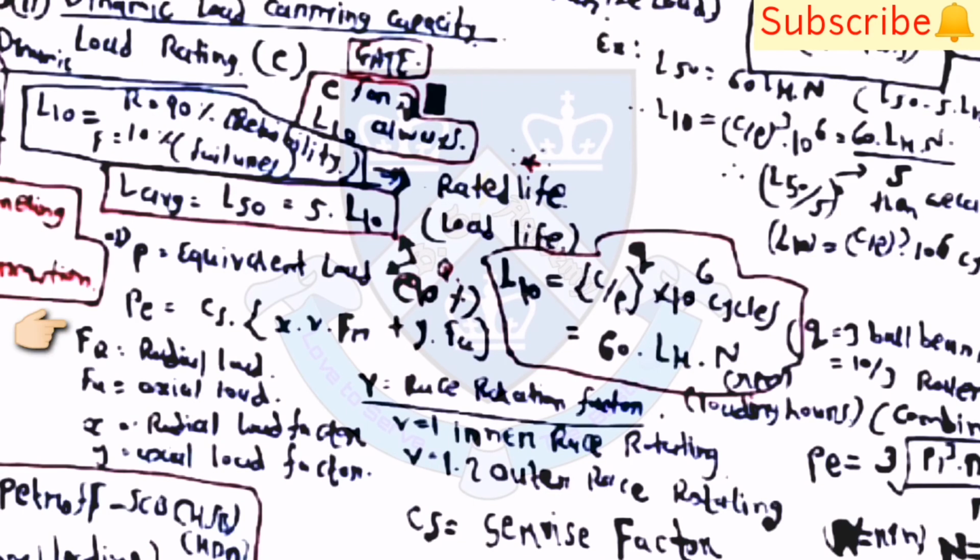Then PE is equal to CS into X into V into FR plus Y into FA. Then L average is equal to L50 is equal to 5 into L10. Then at L10, reliability R is equal to 90%. Then F is equal to 10%, and L10 is also equal to 60 into LH into N.